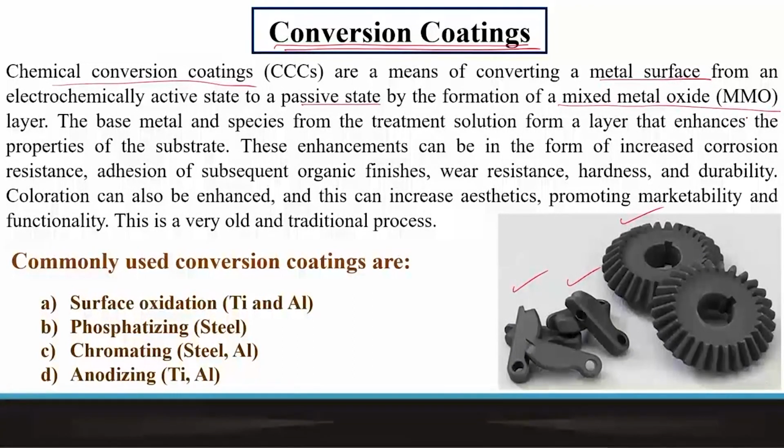And such oxide layer forms on the surface because of this chemical attack. And this is a desired or intentional chemical attack. So, in the process, we actually improve corrosion resistance, we improve the adhesion of subsequent organic coatings or finishes, we improve the wear resistance, we can improve hardness, durability, and so on and so forth. It's a very old and traditional process. It's not one of the most recent ones.